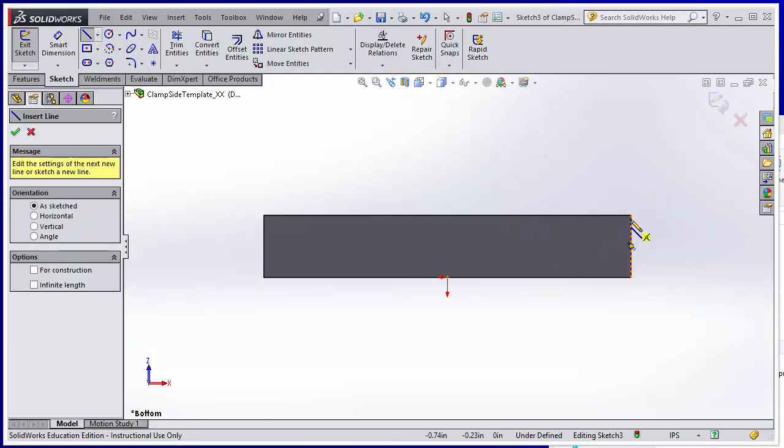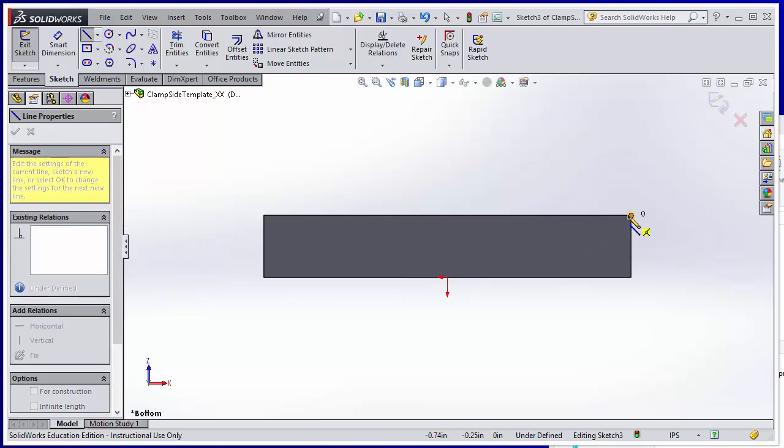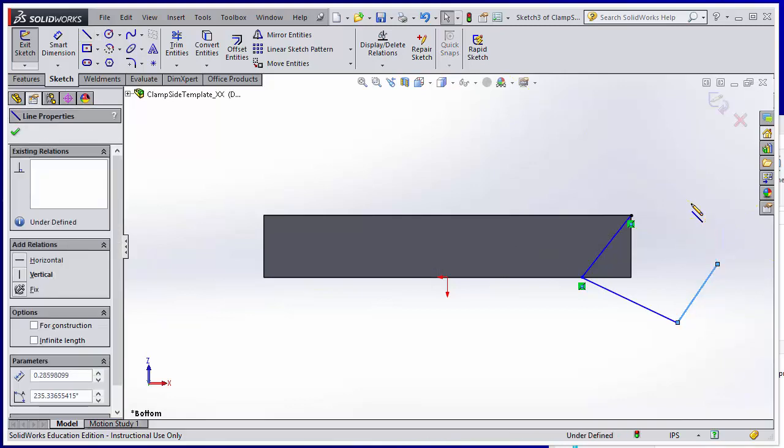You can practice setting the line yourself. Note that when you single click on the opposite side, the line continues so that you can continue setting joints and vertexes, and we could continue this until we close the shape. Now I'll hit Control Z, or up top the Edit Undo button, the Control Z button on the keyboard,